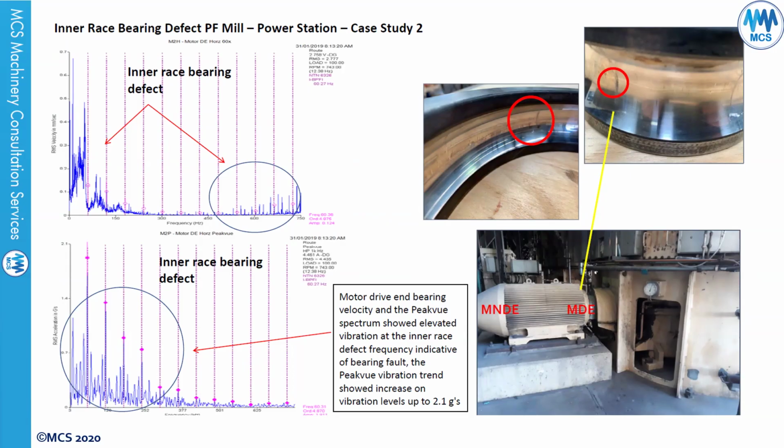As we know, bearing faults are non-synchronous, or non-harmonic, vibration. So when you see, let's say, the running speed with harmonics, and then you start to see non-synchronous vibration with harmonics and sidebands, you start to suspect that this could be a bearing fault. Then, if you haven't already, you feed the software with the bearing number and the running speed of the machine. This should happen before you start the analysis. That is the best practice to make the analysis more accurate and efficient.